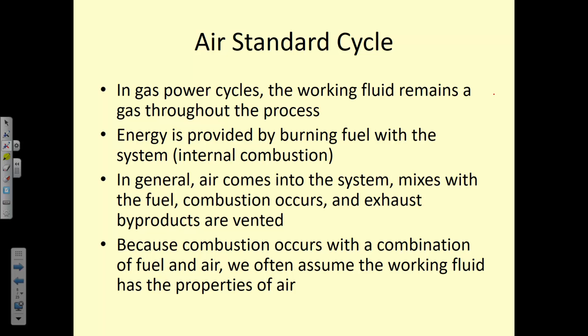When we're analyzing these power cycles, there are some additional assumptions that we should make in order to make analysis even simpler. So we assume that the working fluid is a gas throughout the entire time, so that it's not changing phase. We don't have to worry about that like we do in a steam power engine. It's just a gas. And that the energy is provided by burning fuel with the system.